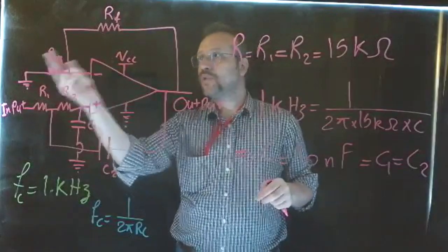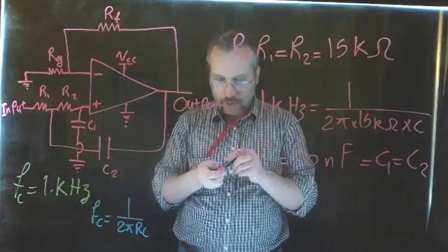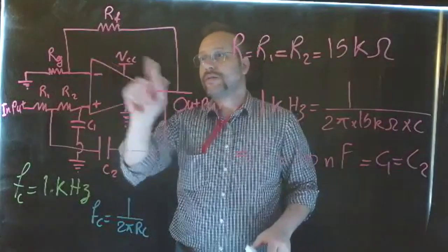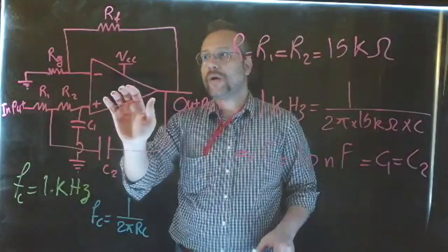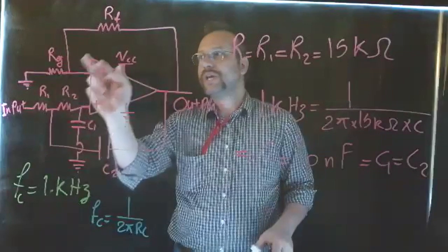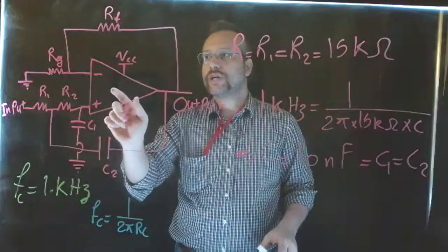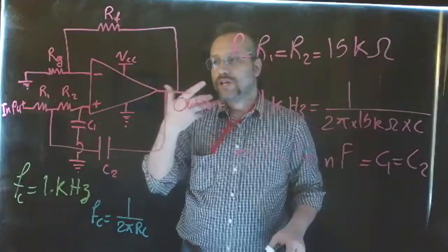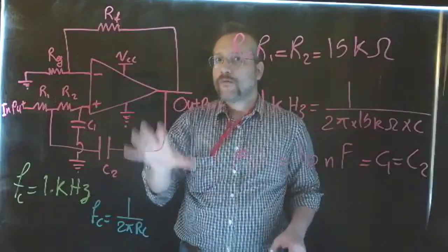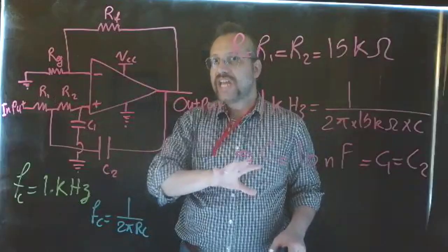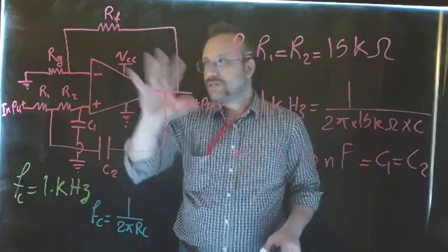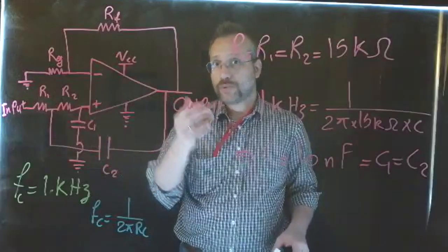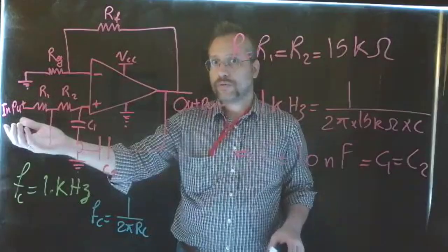But you can see that we have two other resistors that we wanted to set. Now, remember the feedback system in our op-amp actually gives us a gain for our circuit. So what RF and RG basically give us is the voltage gain, how much this circuit would amplify the voltage, the ratio of output over input, okay?